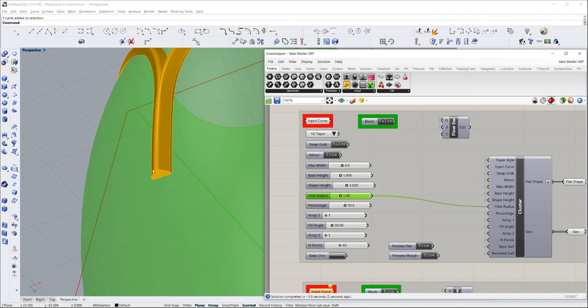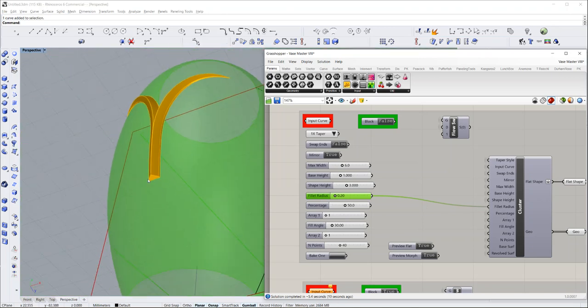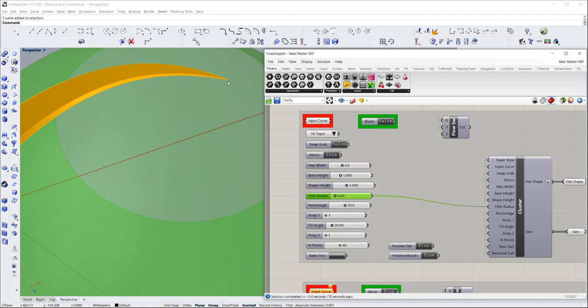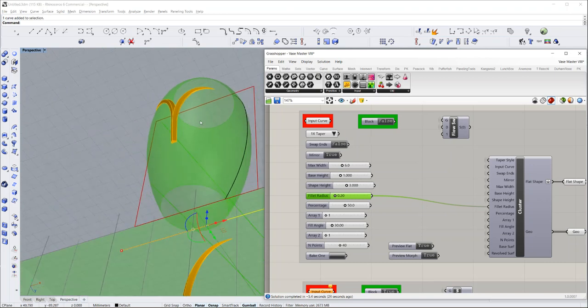Notice that it's now radius to the top. That can be quite handy. Often, as I've been trying this out, I'll set it to something like 0.2, which isn't much of a radius, but it produces a nicer carving. And it also smooths the machine out. Instead of going off a cliff, it goes up and around, so you can see that this is quite small now, but it's there. And by the way, all of these geometric elements taper to a point. Actually, it's not a point, it's a very small flat spot at the very end. And so your height's decreasing all the way, etc.